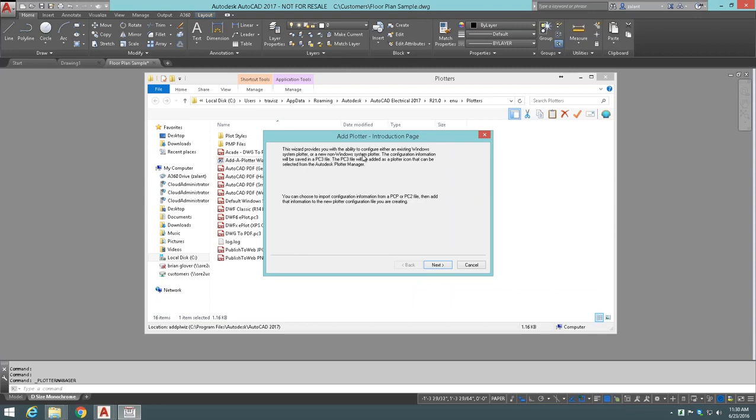Back in the day, you had to get special AutoCAD drivers, HDI drivers, they call them because of the HDI extension, and you had to get them for AutoCAD from the manufacturers like HP or KIP or whoever the manufacturer of your device happened to be. In that case, you would bypass the Windows printing subsystem and send the job directly from AutoCAD to the plotter device via this special driver made just for AutoCAD. With the 2000 release of AutoCAD, we did away with all that and said, look, we can print to any device that you've got installed in Windows, and that is what system printers are here, or Windows system plotters as it's specified here.